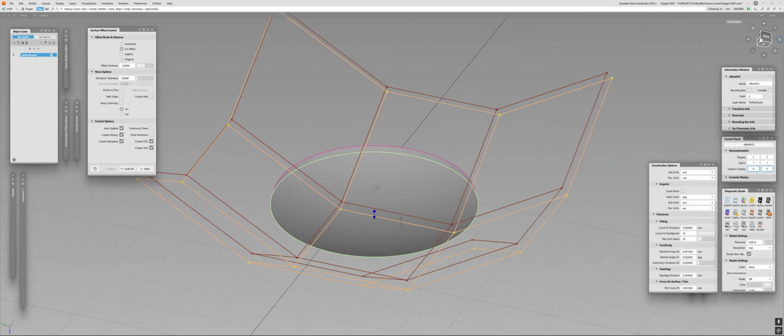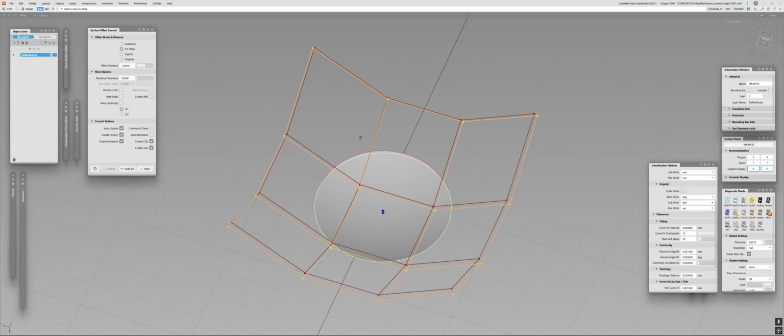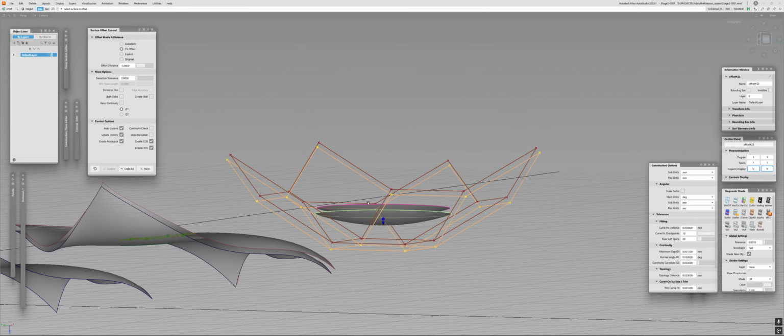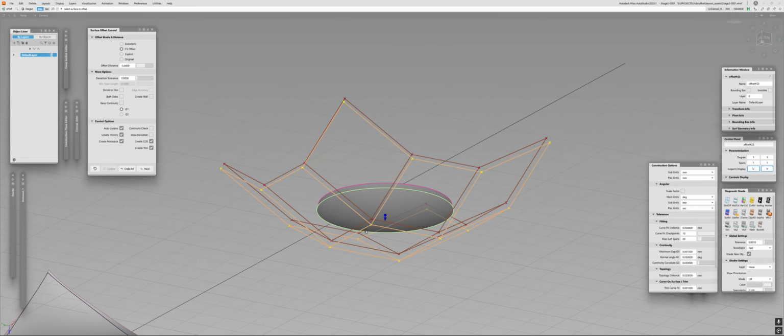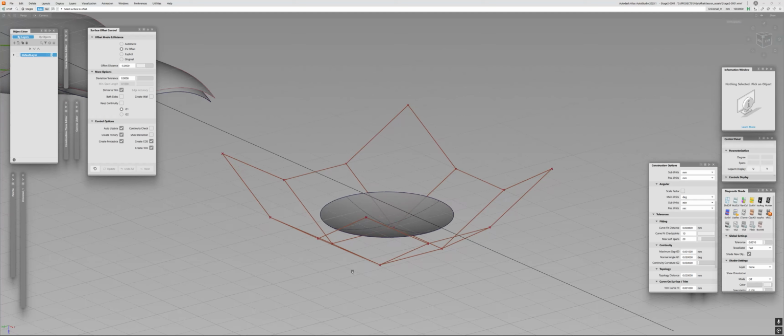As you're going to see, the surface itself is still intact. It has the same domain and the same parameters, but just offset and trimmed. But there can be situations when this is not desirable. When you want the surface which was trimmed after an offset to be contained within the bounding box of an object. The bounding box is basically the cube which holds the trimmed area, and this box reparameterizes the surface. So if I click shrink to trim, let's just try it again.